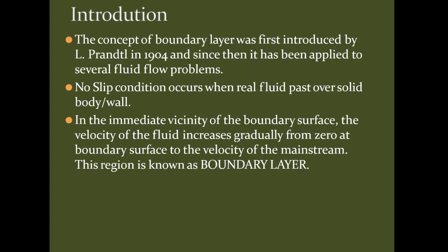So we will see first the introduction. This concept of boundary layer was first introduced by Prandtl in 1904, and since then it has been applied to several fluid flow problems. No slip conditions occur when fluid flows over a solid body or wall. In this boundary layer theory, it was assumed that the flow is over a solid body or a wall, that is a real fluid.